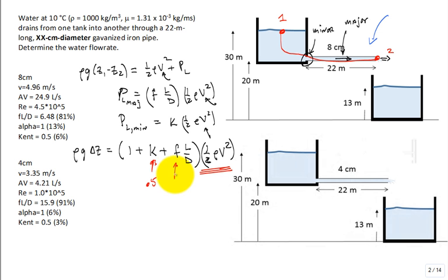And so this friction factor, though, typically comes from the Moody diagram, or also it comes from a correlation or equation, which is a curve fit. Maybe the Colebrook equation, maybe the Haaland equation, or another approximation. There's quite a few of them out there. The textbook has a great one, recently developed, but it's set up for computer implementation. It's really not set up for hand calculations. It's an equation that curve fits the Moody diagram, and does it really well.